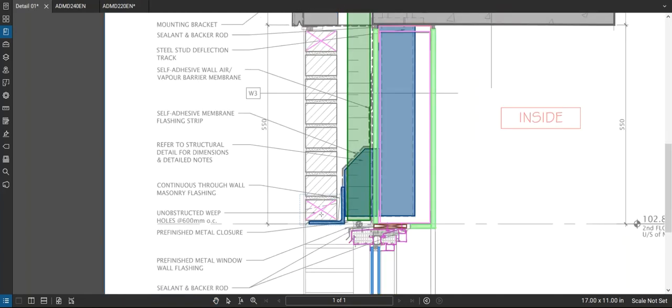Okay, so vent holes at the top, weep holes at the bottom, airspace behind, minimum 25 millimeters airspace. This allows air circulation through this thing. Brick's porous, so water could be running down the backside of this thing. It allows it to weep out right here.